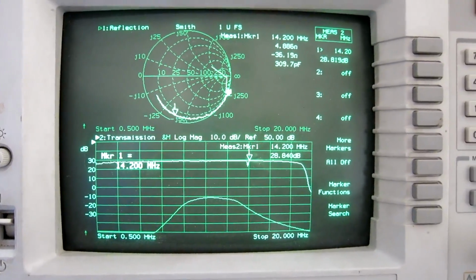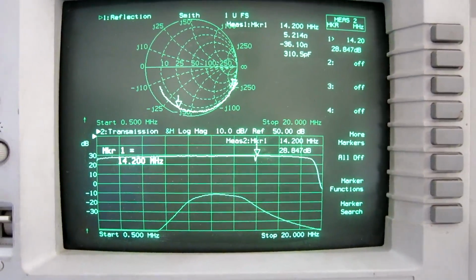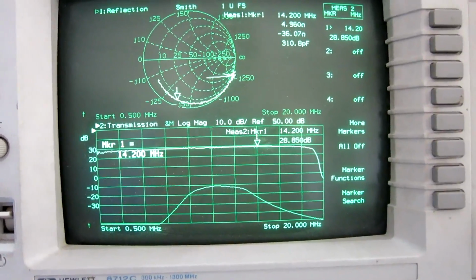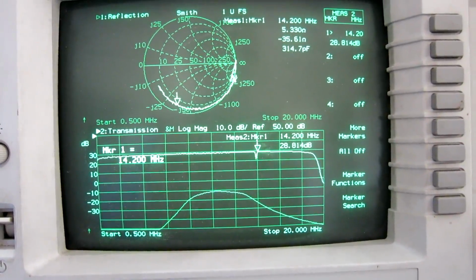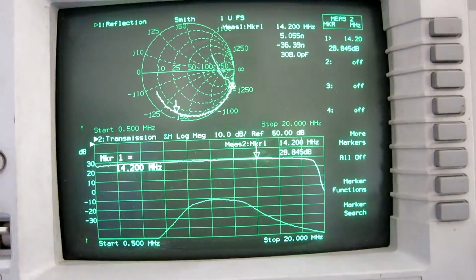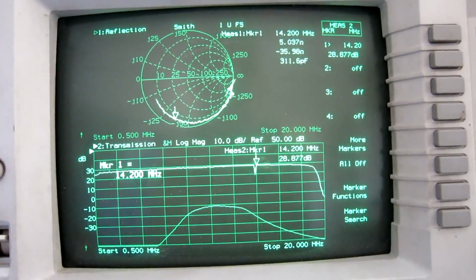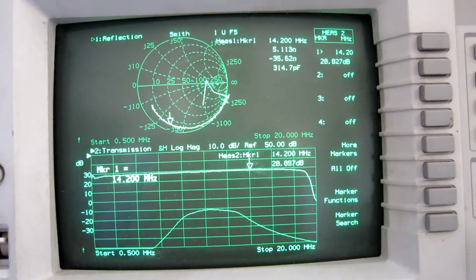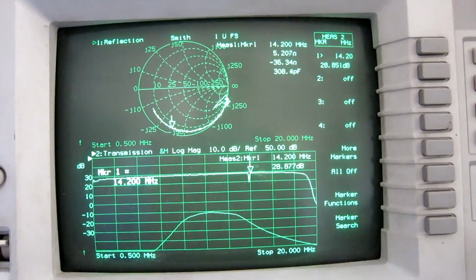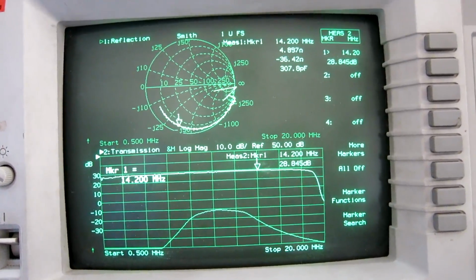It's 28 or 29 dB. So this antenna gives 10 dB more signal to the radios, but still the margin with the tuned antenna is 29 dB. So in this location both radios are seriously overqualified, at least for 20 meters.